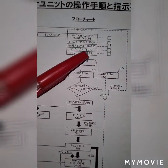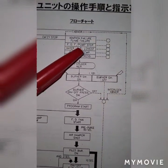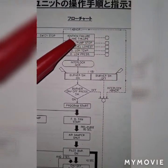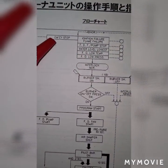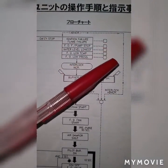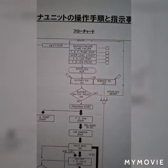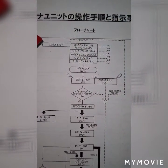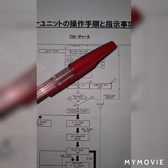These alarms, together with the emergency stop switch, will give a safety interlock with the boiler. Having these alarms, you can no longer start the boiler in automatic mode.